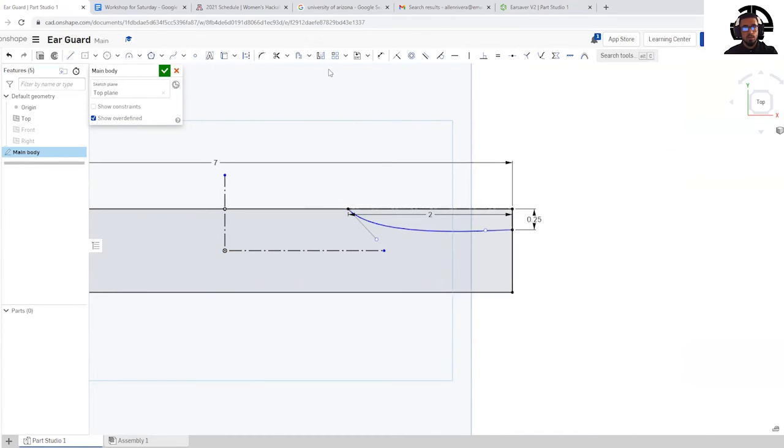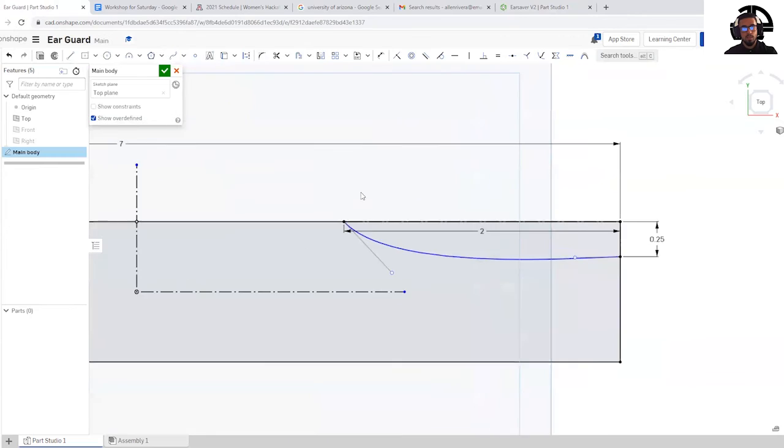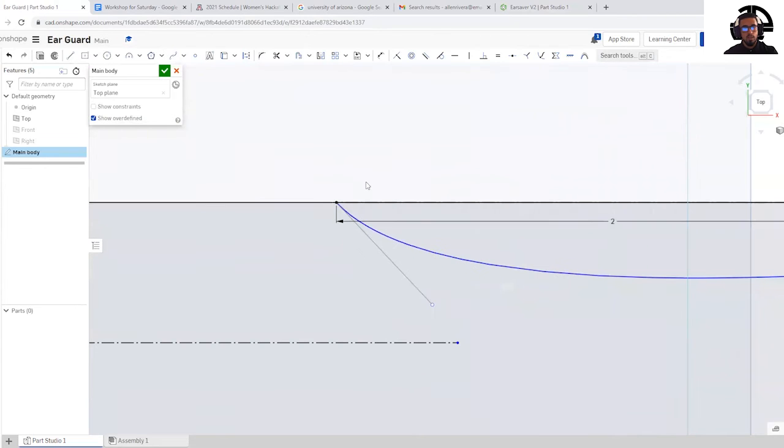And now I'm going to use this button right here. You see an object that has a line and then it gets mirrored over in the opposite manner, which is exactly what we need for this line. But first, let me just do something to add a little bit of a sleeker design aspect to it. So this button right here is called the sketch fillet.